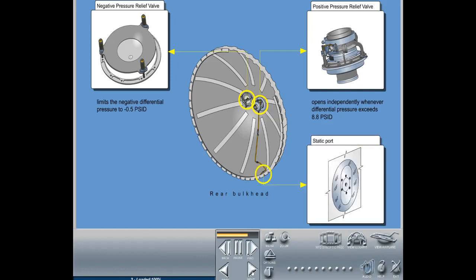The static pressure port senses the ambient static pressure and transmits it to the safety valve in order to allow the overpressure relief device to work. The static port is electrically heated in order to assure there are no obstructions of sensing orifices due to icing.